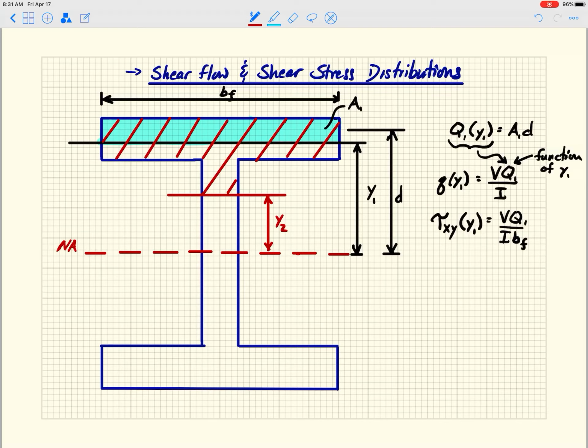right, that I am taking the Q for, the capital Q, the first moment of the area. And then I'm going to dimension, and you can see I'm going to put a, so that is the universal symbol for centroid, and if I dimension to that location, that is going to be my D, right?